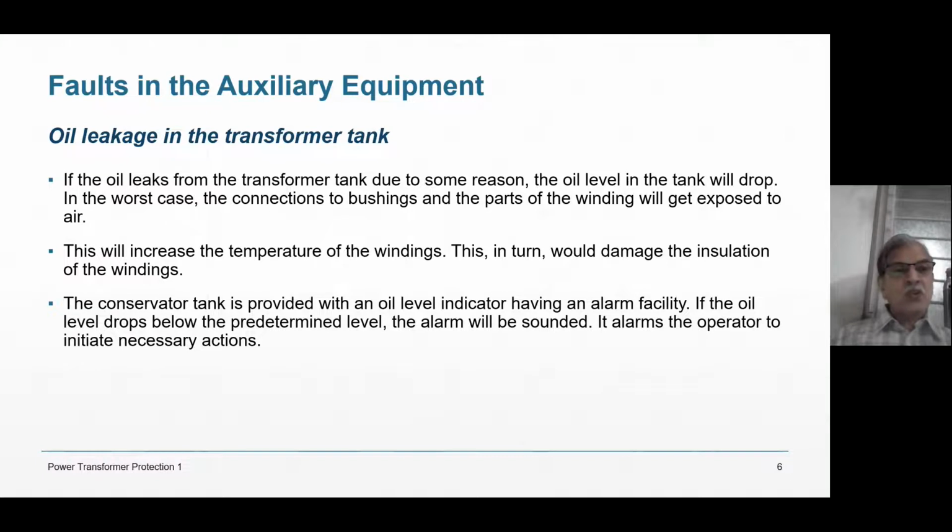Similarly, in the oil, the gases also should not be there. The air that is filled, the dissolved gases, some gases which are conducting, some gases which are harmful, some gases which make chemical reaction should not be there. Also, the mechanical impurities, because you see when you are drilling and doing machining of the transformer tank, at that time some mechanical parts are left. So those mechanical impurities are also required to be removed. So these things are very important when you are commissioning the transformer.